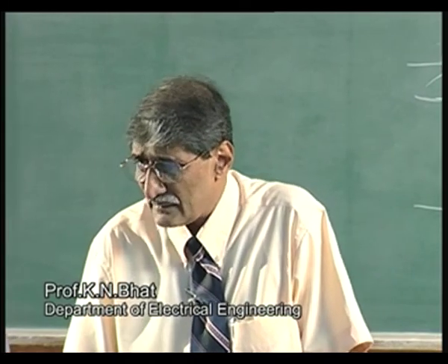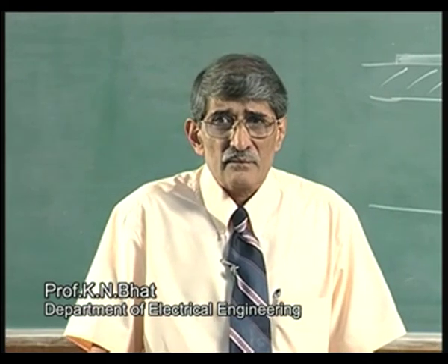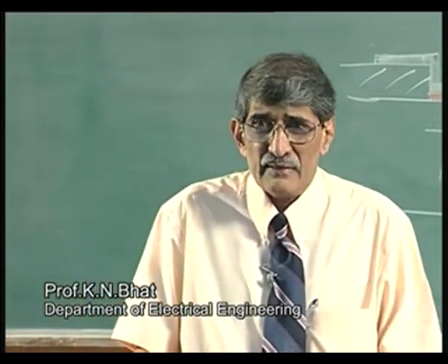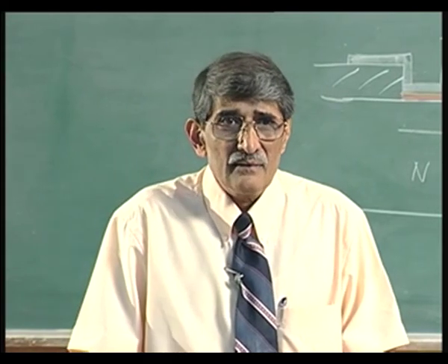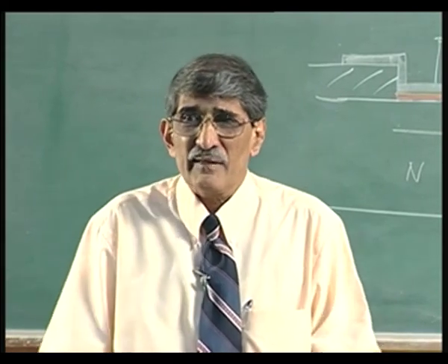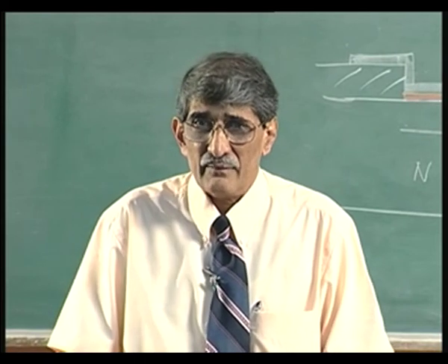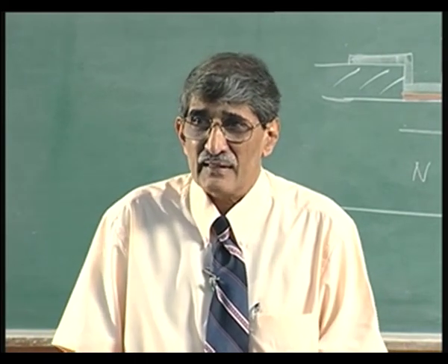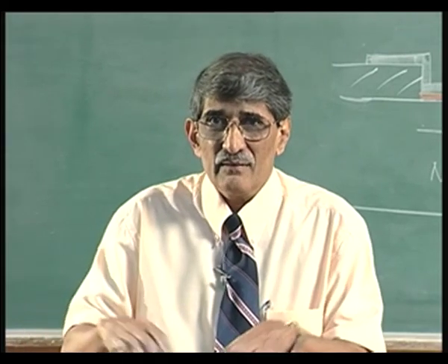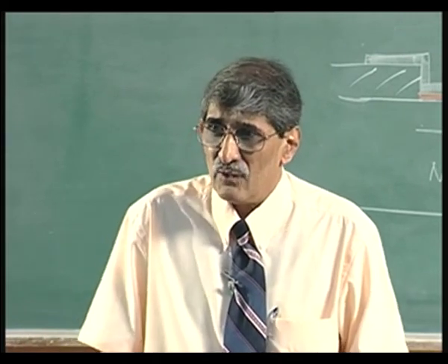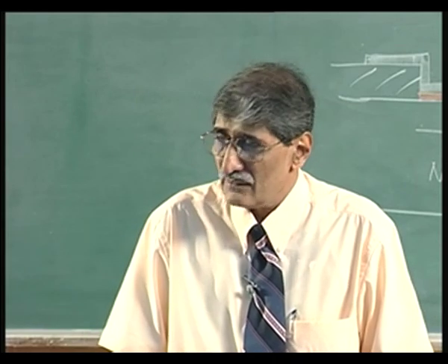So, I think with that we have completed our discussion on the Schottky barrier diode. We have seen idealities, non-idealities, everything. The main thing that you would require is in the reverse bias operation, how does it behave, and you should know how to cut down the reverse leakage current. Those techniques also we have seen here: by providing a field plate, by oxide and metal running over the oxide, we can reduce that current. So, all that we have seen.